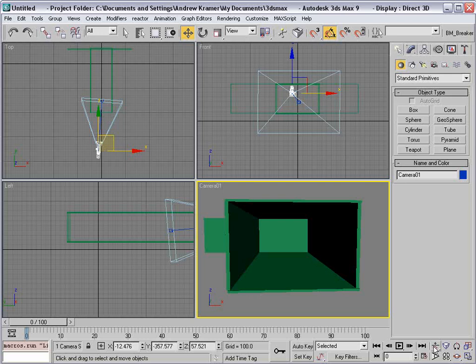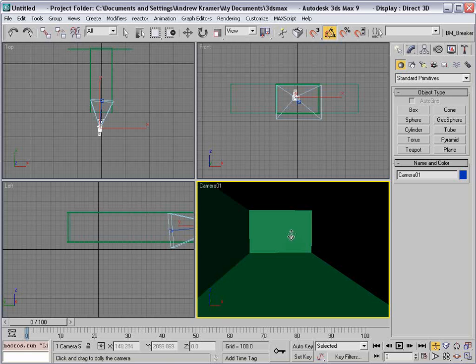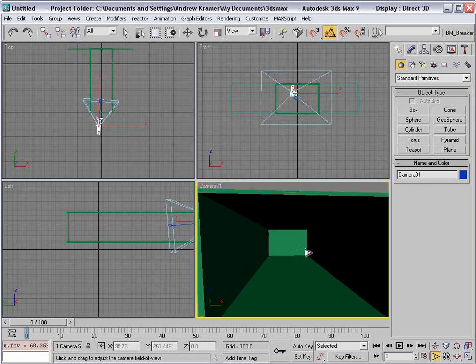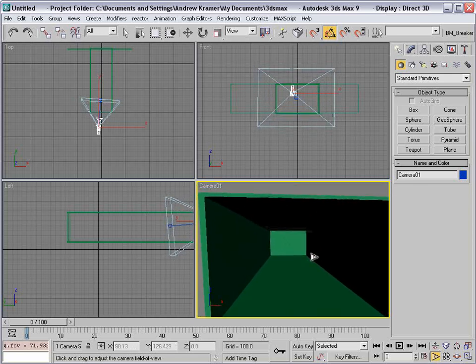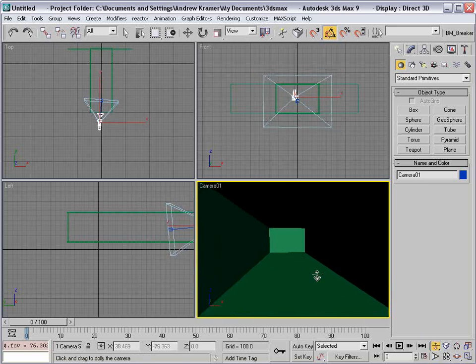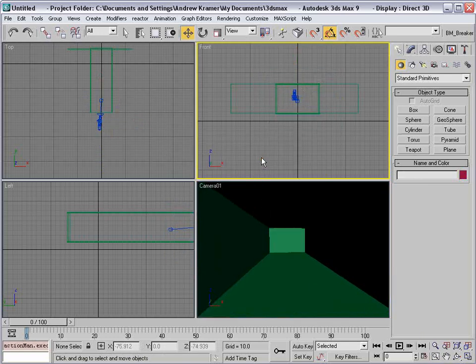So I'm going to take the dolly truck tool, and we're going to kind of push in here and move it into just a little better position, and then this tool is going to open up the field of view and basically zoom the camera out, and that way I have sort of a wide angle lens, and that just looks a lot cooler. So this is the setup part, creating this room. The real stuff is going to happen once we start creating those vines.